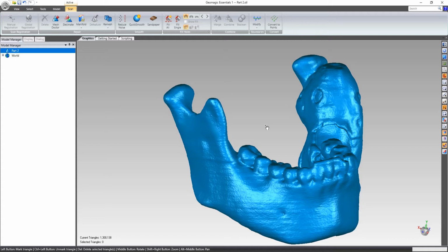Auto-surfacing is the Geomagic process to create a NURBS surface model. Auto-surfacing consists of 3 different layers of spline networks. The first layer is called the contour curve network. The second layer is called the patch curve network. The third layer is called the grid network. All of these spline networks are connected to each other to create surface patches, which are fit all around the part.